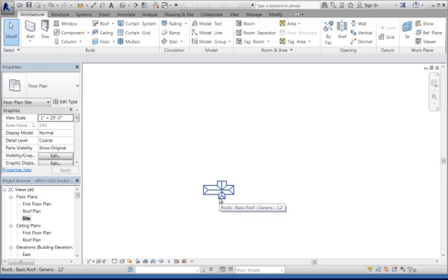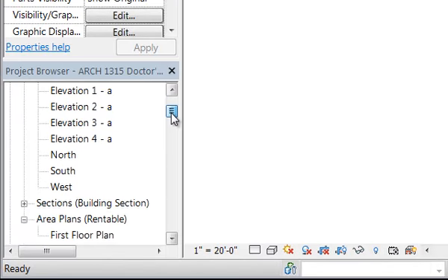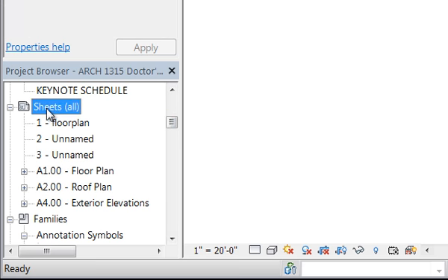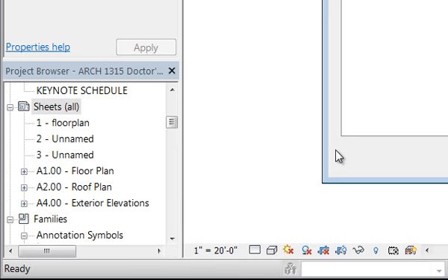So I'm looking now at our assignment sheet. It says architectural site plan. It's going to be sheet C100. So you're going to make a sheet down in your sheet section. I'll just show you real quick, review how to do that. New sheet. It's going to be on our D22 by 34.